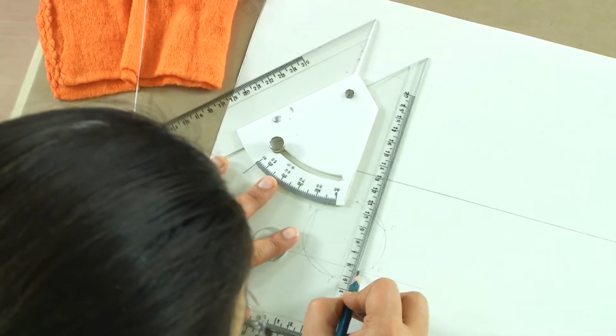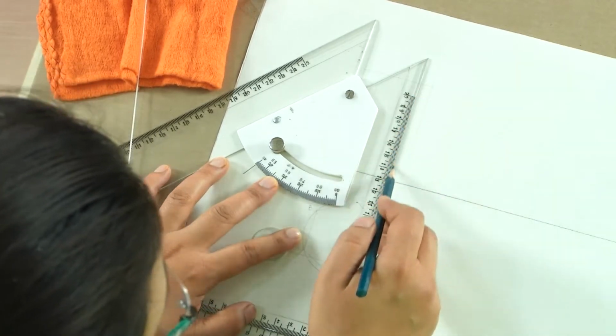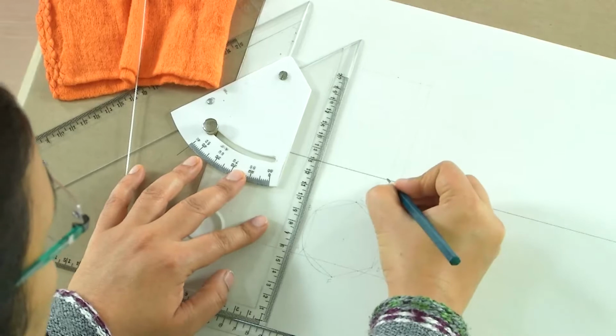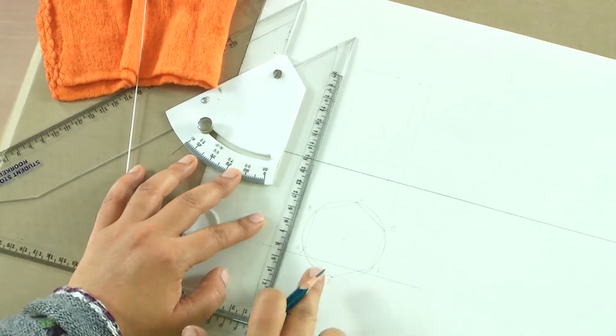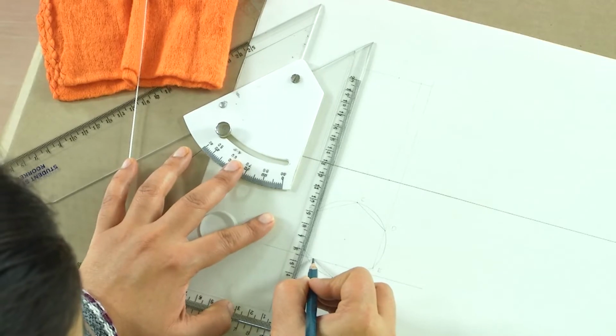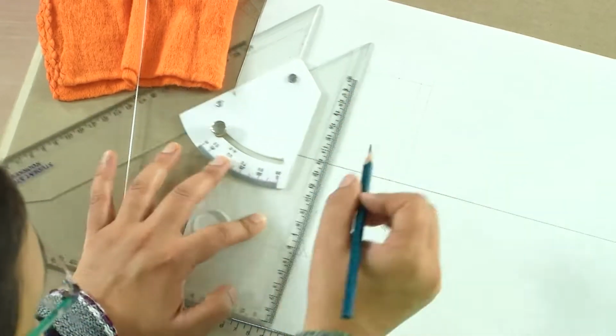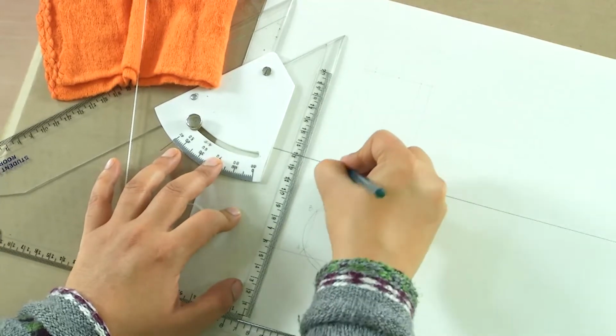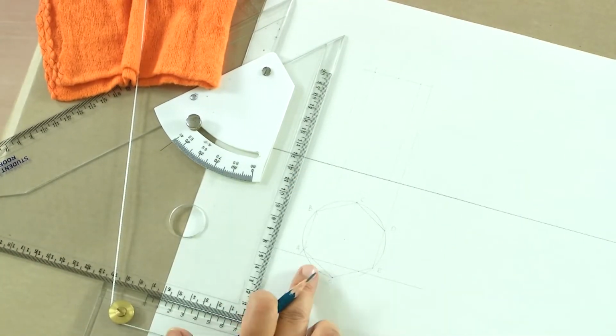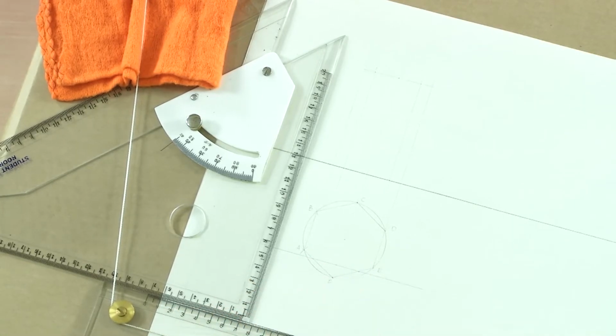I draw a line to meet this E, F here, and in the base, the lower one here, and similarly we get another line which is intersecting the top base and the bottom base here. And what is this going to be seen as? This is going to be seen as a rectangle. If you remember our initial introductory lecture, we said that if the plane is going to be parallel to the axis or perpendicular to the bases, we will always be seeing a rectangle. And now in this case, I will quickly darken it.